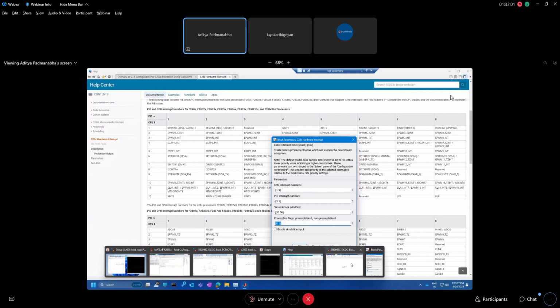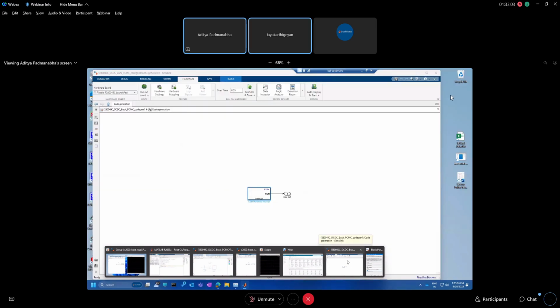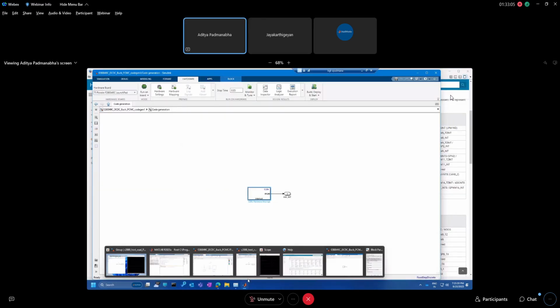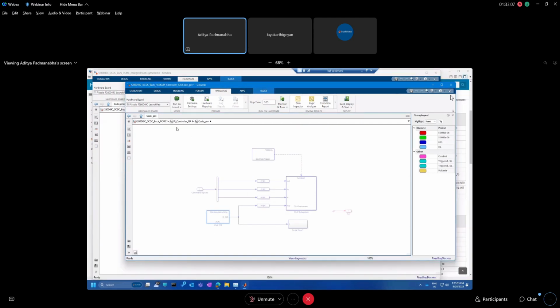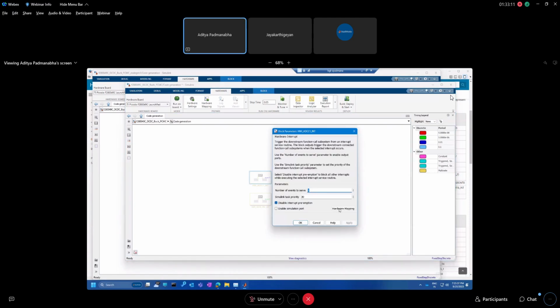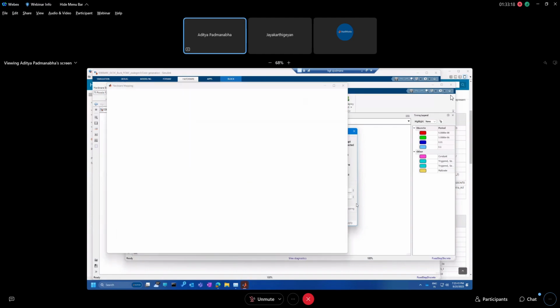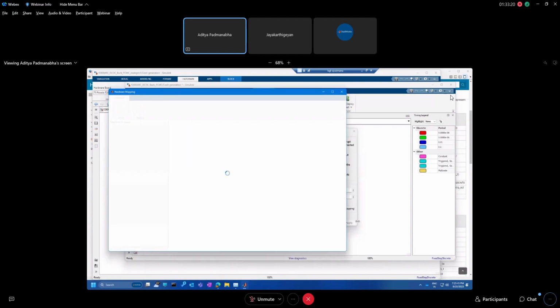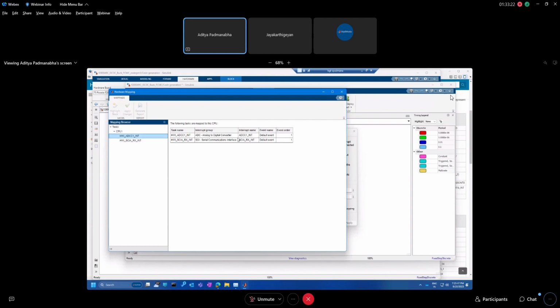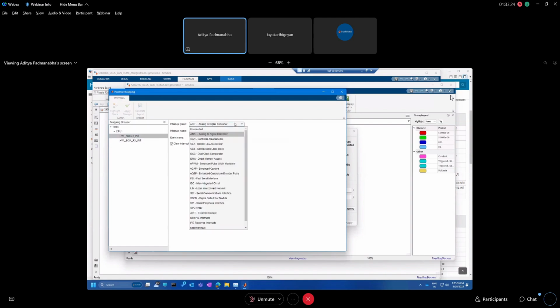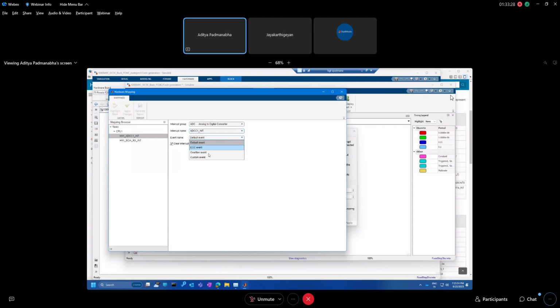And in the 23A release, along with this hardware interrupt, we have a new hardware interrupt block, which is easy to configure in terms of selection. On the block, you can see the number of interrupts and ceiling task priority settings, and then you can open the hardware mapping, pick whichever interrupt you want, select which event you want to trigger an interrupt and configure it.